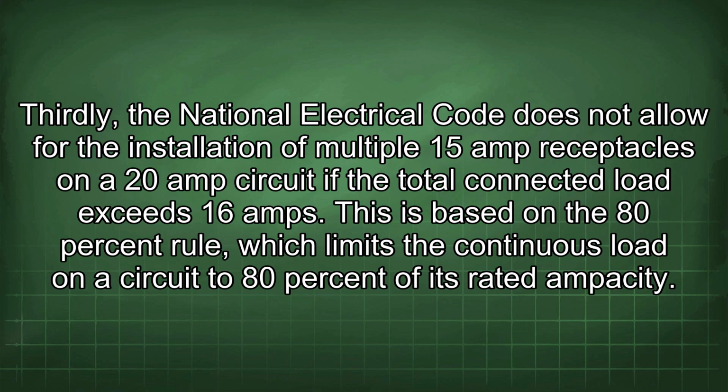Thirdly, the National Electrical Code does not allow for the installation of multiple 15 amp receptacles on a 20 amp circuit if the total connected load exceeds 16 amps.